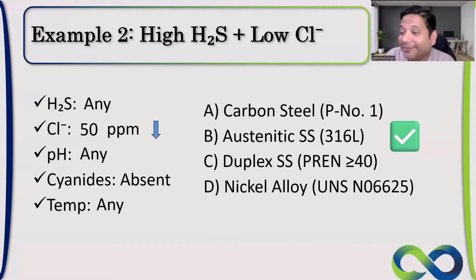Okay. So I'm taking very few examples, Rajan. I'll not be covering everything because otherwise it will become confusing. So I'm trying to draw some lines for the uses. 304 is very less used. The limitations are much higher on that. 316L you can use for wide application.